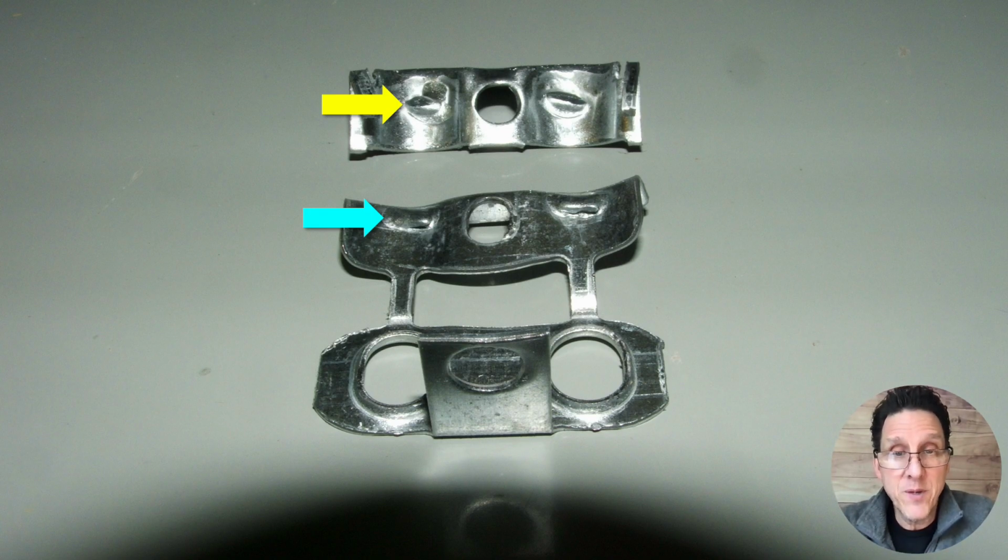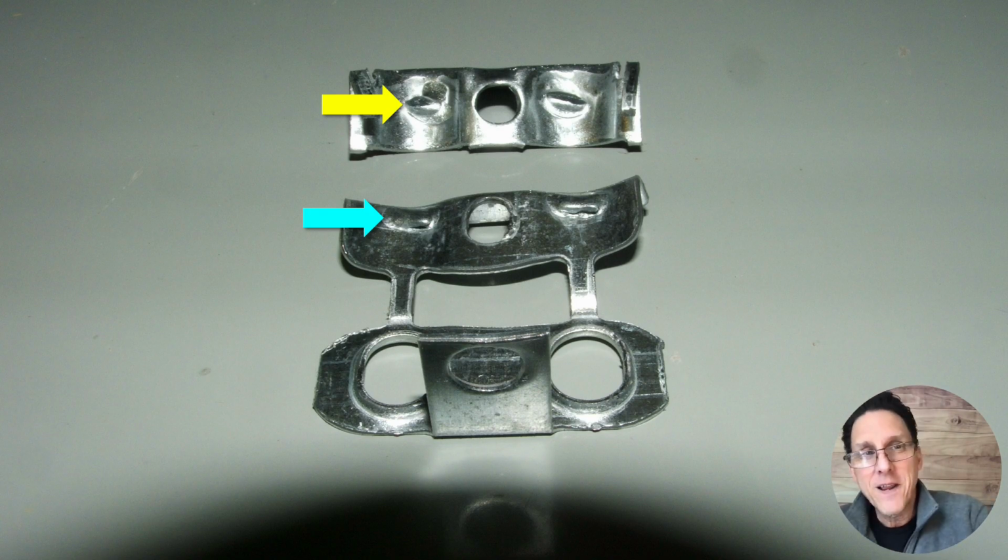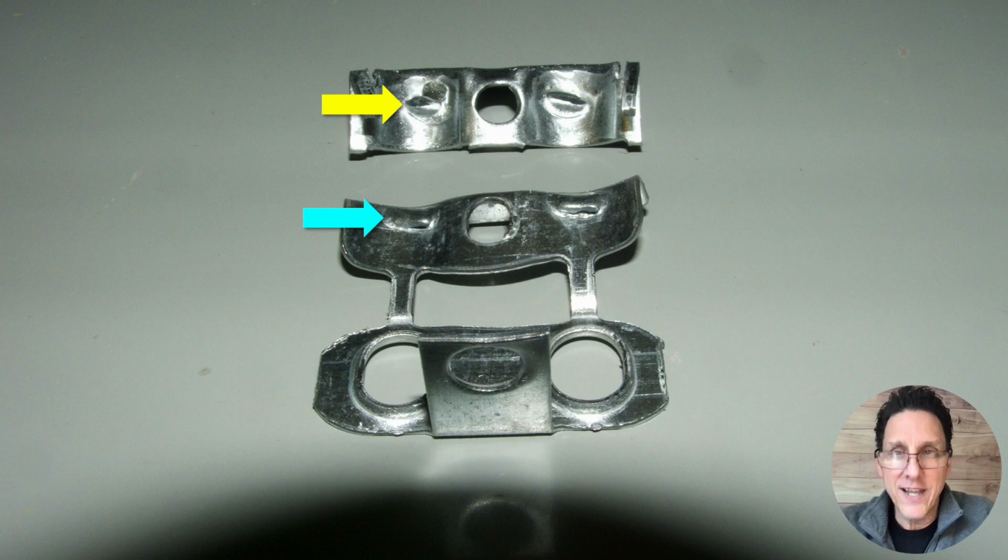Now, what I have seen people do in a pinch, they did not have any more clamps like the top one where the yellow arrow is. But they did have clamps, or they stole a clamp out of another box, like the one on the bottom, and they used it with NM. But what they did was they cut it. They cut the clamp down, and they got rid of the parts that kind of make it look like it's not suitable for NM cable, right? Well, you can't do that, right? That clamp is not made for NM cable.